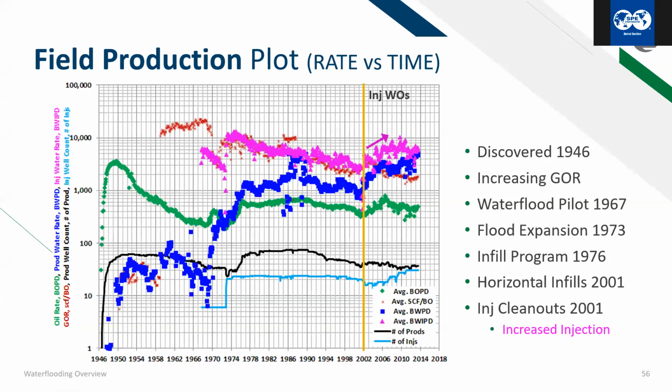The importance of knowing about the cleanouts is that it means that the water they're cycling is not being cleaned as well as it needs to be cleaned. There's probably an economic reason for that, but it's causing the injection perfs to get plugged over time. So it's something to look out for again in the future.